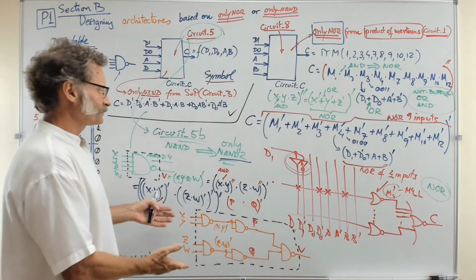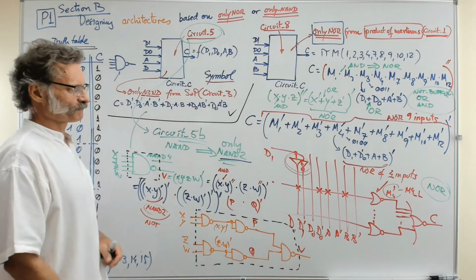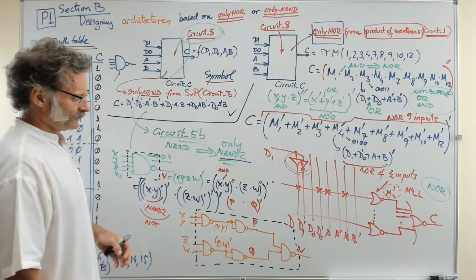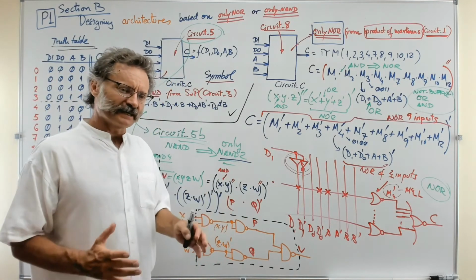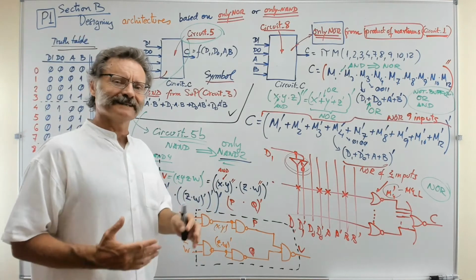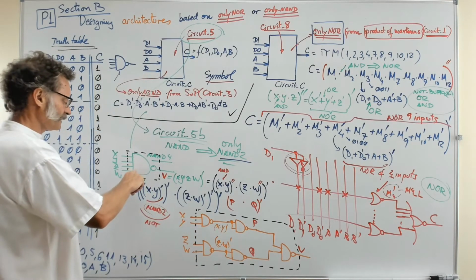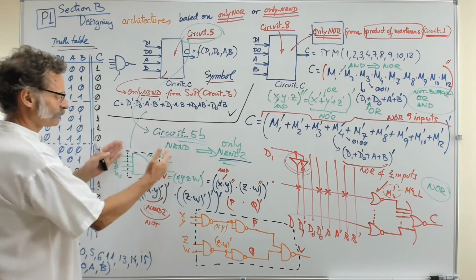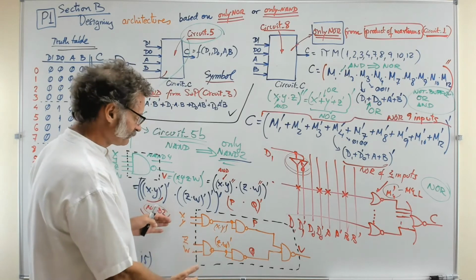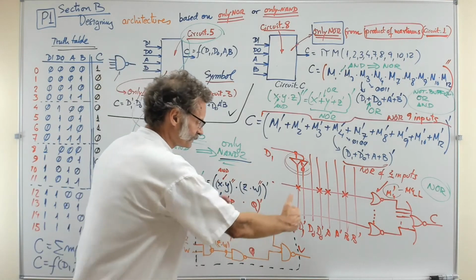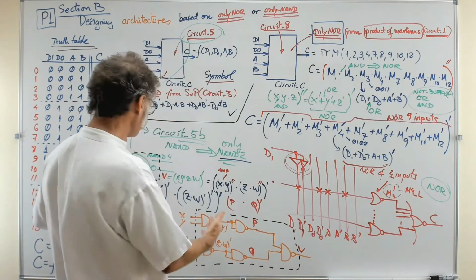And that has to be solved for every single NAND that has more than 2 inputs. And that way, in the end, the circuit becomes a circuit that is very constrained. It is a circuit based on only NAND of 2 inputs, and you have here one level of gates, if you like. This 4-input NAND gate is one level of gate, and that one, which is the same logic equivalency, now has 1, 2 and 3 levels of gates, and that is going to take more time to execute the computing of the function, you see.